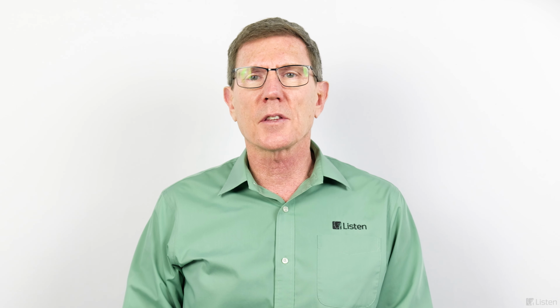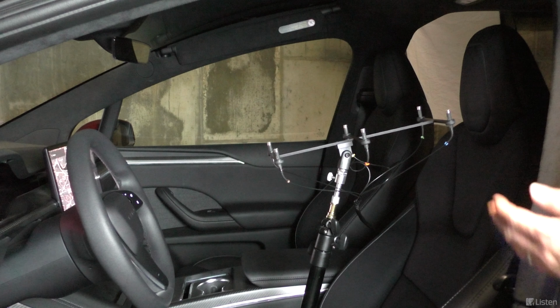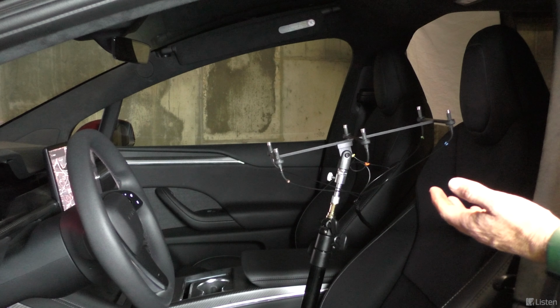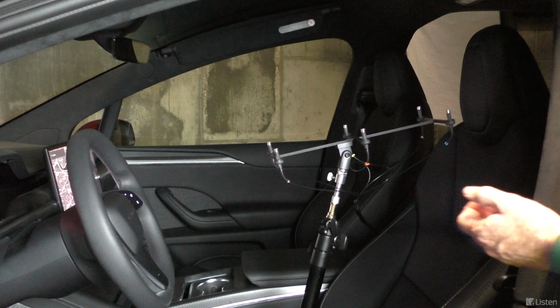Today I'm going to continue on from our last automotive video where we measured frequency response, spectral uniformity, THD, and IM distortion. This time we'll demonstrate Max SPL at the onset of audible distortion and impulsive distortion. Let's make some measurements. Again, I'm using the test configuration recommended in the AES TCAA white paper on automotive measurements.